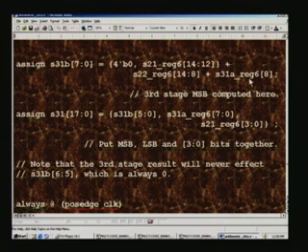So, to this we had to add the carry resulting from the LSB addition, which we had done earlier, and that is also to be done without fail, and this will give you the third stage MSB computation, and you have to concatenate all the results put together. We had done the LSB computation earlier, and here we are doing the MSB. We had to put them together, that is by concatenation, that is what we are doing here.